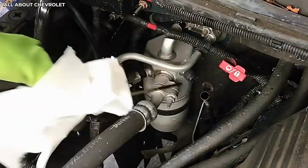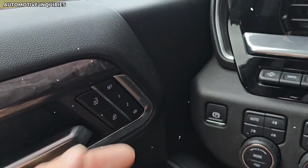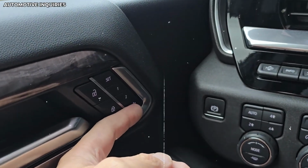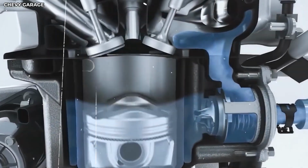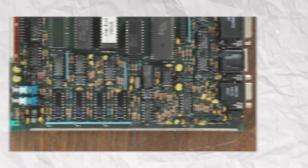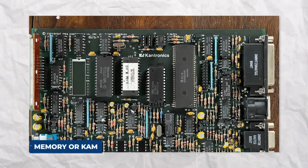The truck feels lazy and unresponsive because there's a growing gap between what you're requesting and what the computer actually delivers. The ECU stores this learned behavior in adaptive memory, sometimes called Keep Alive Memory, or KAM.